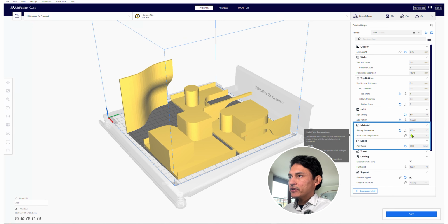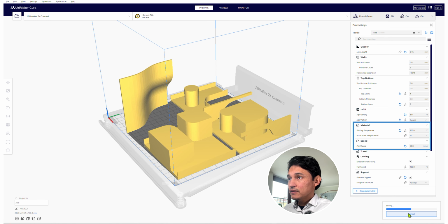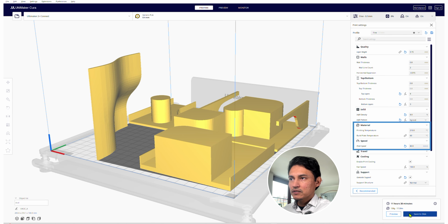These two values are directly proportional. That means that if the nozzle gets hotter, you can increase the velocity of the printing. Nevertheless, I would suggest never to print over 210 Celsius with PLA, so you avoid getting toxic fumes. And I also suggest you to choose the velocity according to the quality you want to achieve. If you want high quality, then you should lower the velocity, and for lower quality, increase the velocity. But it may happen that the extrusion velocity of the filament doesn't follow, so you end up with bad results. A good speed for 3D printing with PLA would be around 50 to 80 mm per second.